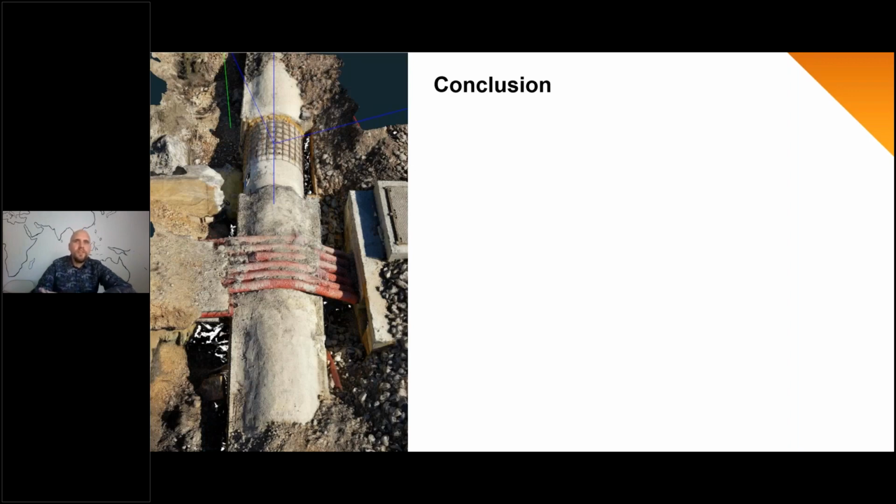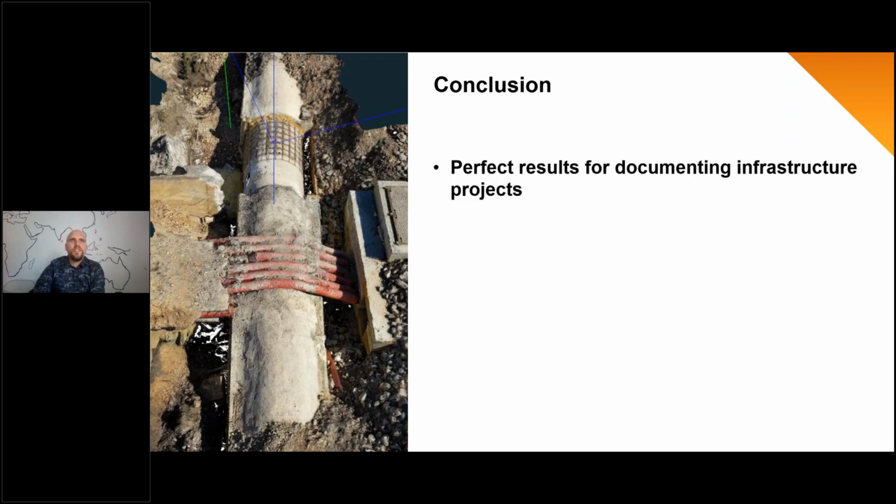So in our opinion, this videogrammetry technique is perfect for documenting infrastructure projects because we usually are interested in data that has fine detail. We have long and narrow objects of interest, so these are perfect to record video of. And then in the video, all the important details will be seen. We'll be able to see from the 3D model where we have concrete, where there is no concrete. We'll be exactly able to see where these pipes are going into shafts and so on. We can see what kind of insulation we have on our pipes and so on.